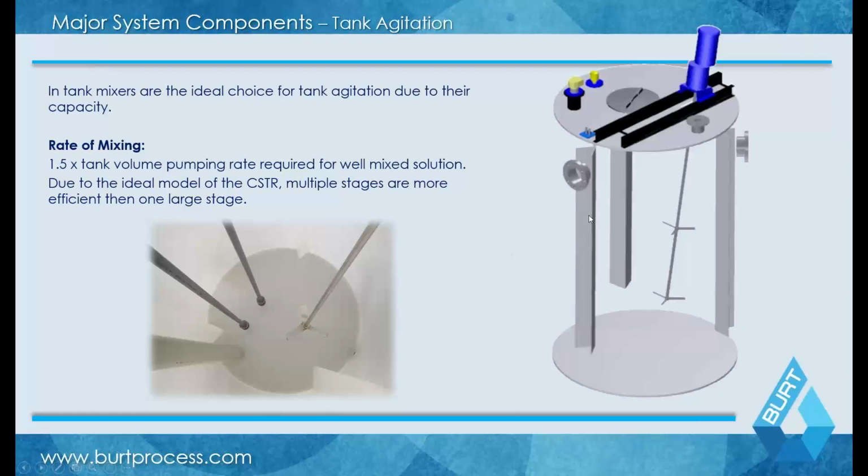Looking at a cutaway of a 3D model, you can see something very similar. The waste comes in, is directed to the bottom of the tank, goes into the mixer at that point, and then essentially is allowed to flow out in most of these cases. You can comfortably treat about 2.5 to 3 pH units in a single pH neutralization tank. Sometimes you do end up putting these tanks in series, barring other outside considerations for treatment.